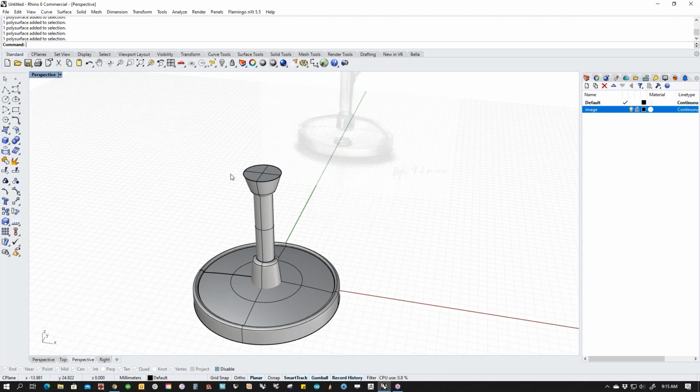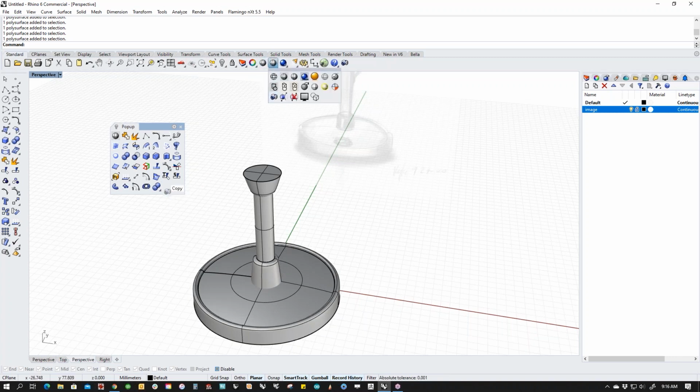I can then close it and then that tool would be in my pop-up for good. Now, one thing I want to point out is if you do this, make sure that when you're copying things, you use control, not shift. See how it says move edit? If I were to move this, it's going to actually remove it from this toolbar and put it in this toolbar, which is great, except for the fact that it's no longer in this toolbar. So if I delete it from here, I've just deleted the tool. And I don't want to do that. I'm going to have to use toolbar reset and lose all my customization. So we don't want to do that. So make sure that you're using control, which is the copy, right? We want to copy it.